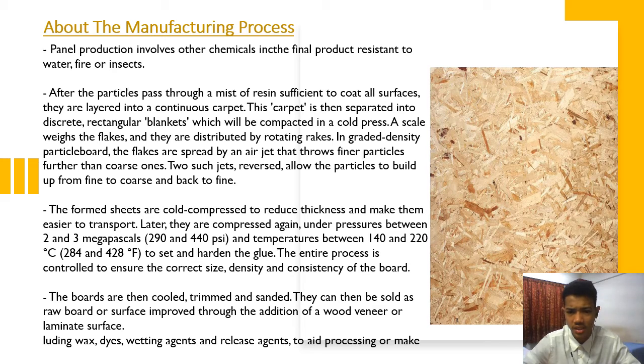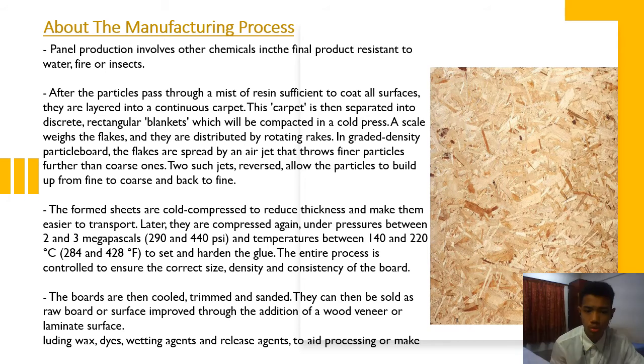In grading this particle board, the flakes are split by an air stream that throws finer particles further, which allows the particles to build up from fine to coarse and back to fine.